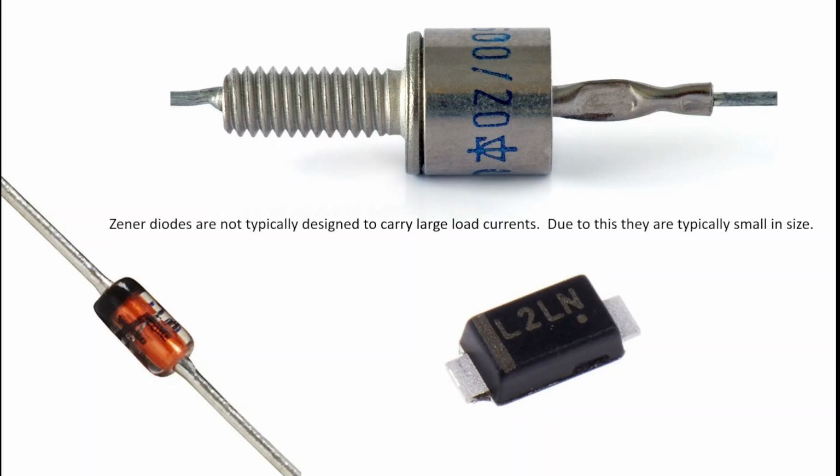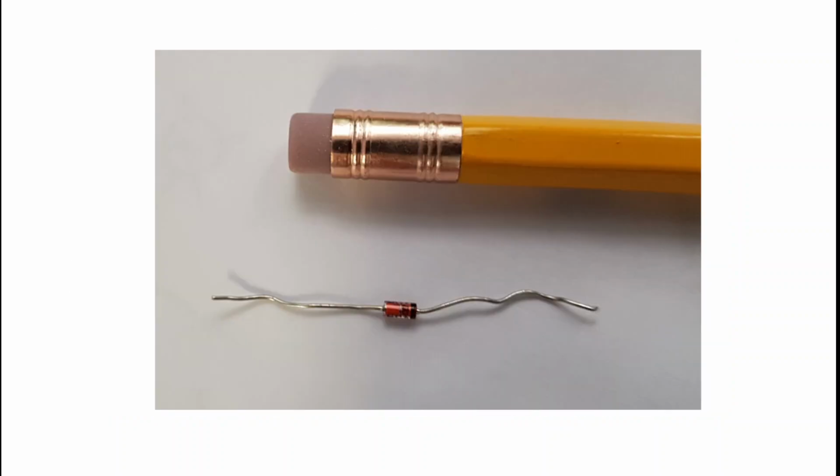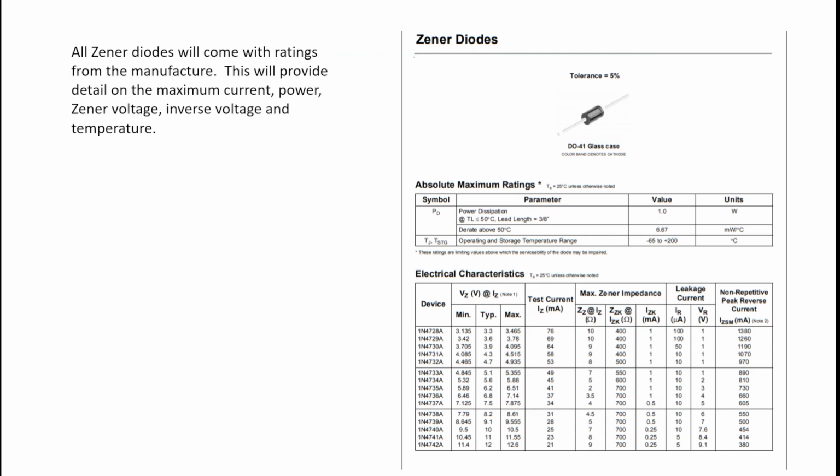Zener diodes are not typically designed to carry humongous load currents, and due to this, they're typically smaller in size than what you would expect from a standard diode. So we can see here a Zener diode, the glass sort of one. This one looks like it's connected to a circuit board. That's a stud mount. There, for comparison, that's a pretty small Zener diode compared to a diode on the left. And if we compare it against a pencil, that is significantly different. All Zener diodes will come with ratings from the manufacturer, and this will provide detail on the maximum current, power, Zener voltage, inverse voltage, and temperature.